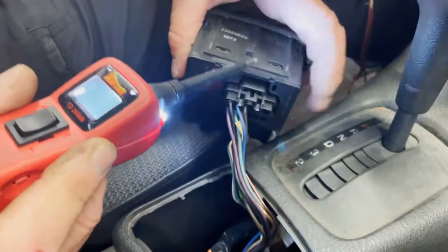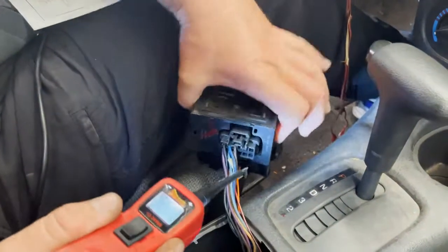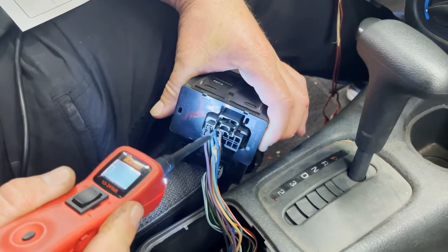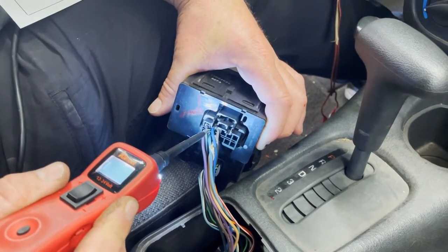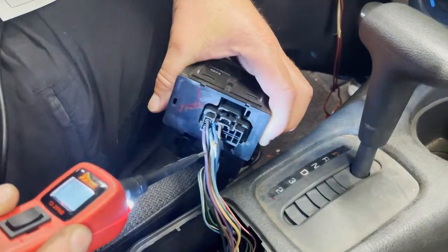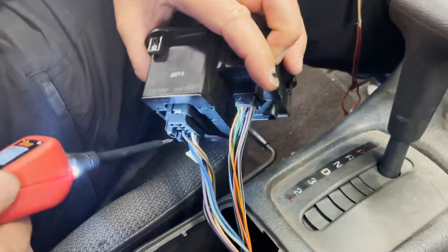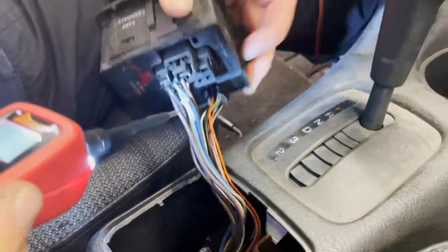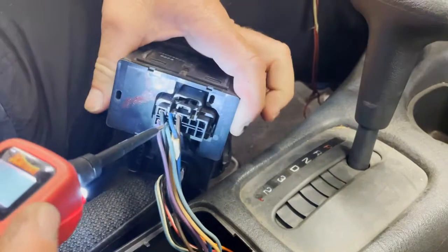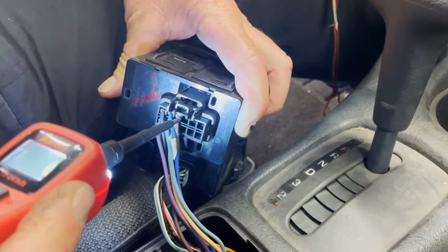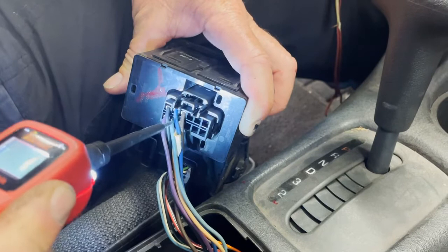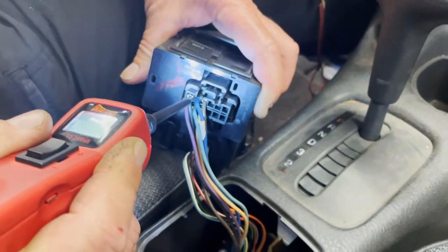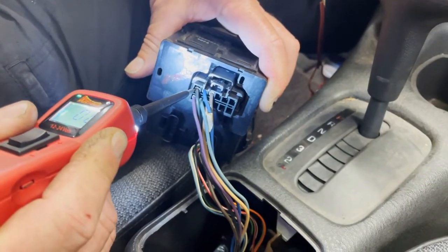So now what the switches do, the switches apply that power and ground to either the driver's door, which is the dark blue and the brown, or the passenger door, which looks like the tan and the light blue. So we're working on the driver's door. All right, so the switches send ground to all the wires right now. So all 4 wires have ground, and they're getting the ground from this black wire.